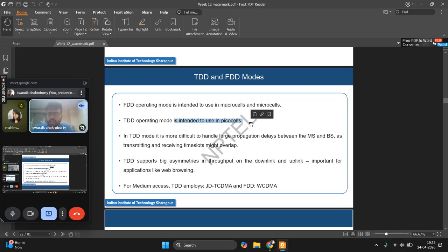So the advantage of time division is that you can allow a signal to access the entire bandwidth at a time. If the signal has reached its time slot, then it can take advantage of the entire bandwidth, whereas in FDD, it has to satisfy itself with a fraction of the bandwidth.